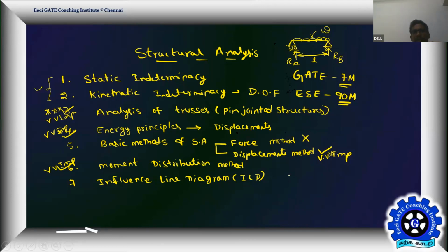Then you should be in a position to estimate what is the maximum possible load coming onto the bridge, and what are the maximum reactions, like support reactions, bending moment, and shear force. We're going to find that out. How do you find all these things when there is a load moving from one end to the other end? For that, we need to have some methodology.